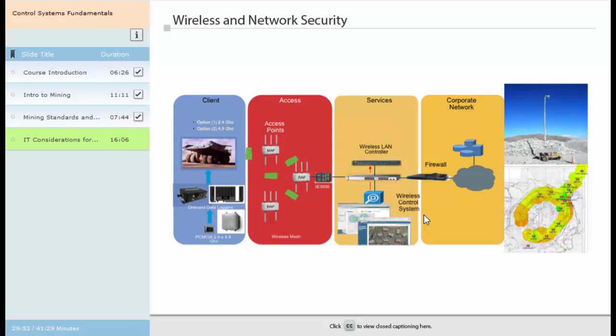While these network advancements improve mining efficiency, they also open the mining industry up to potential security risk. Mining networks need to take into consideration additional security measures, such as firewalls used at the DMZ for securing the field network from the corporate network, VPN access used to provide remote access for technicians in the field to process status information, strong encryption for securing wireless communication from field devices to the control network and corporate network as required, and port security on access points via 802.1x to authenticate users to the network.